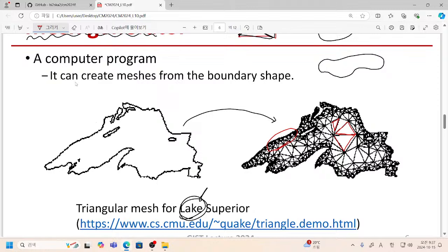This is quite similar to our case. How about our requirement for mesh points? If we have silicon here as a channel, then what we have to do is introduce fine resolution for the surface region and relatively coarse graining for the center part, if this silicon nanosheet is quite large.